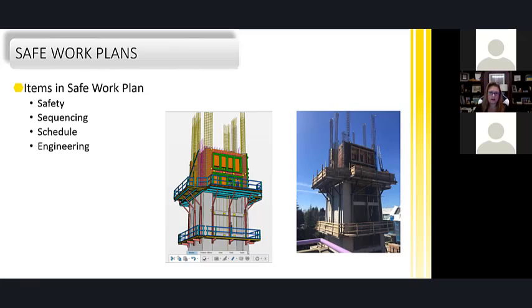Not all companies do this here. I'm a real stickler for this. This is important to us. So you quickly identify all the steps that are not always obvious to complete. And then typically, a site safety or safe work plan identifies the sequencing of the installation on a plan or a drawing. I like the plan view drawing, and then we identify what's going to go first, what's going to go second. This also helps lead into two-week and three-week look-aheads for the foreman for the site.